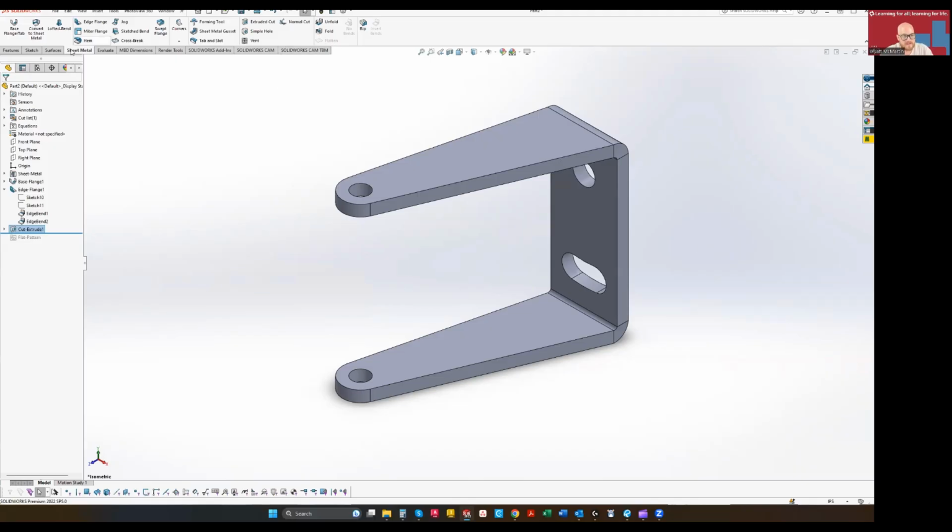However, you'll notice in the sheet metal tab, we don't have an option to flatten it. However, we do have a flat pattern in our feature tree. It just by default is rolled back. So if we just grab this little blue line and drop it underneath our flat pattern, now it's still suppressed here. So it's not bolded like these other ones are here. We can now have the option to flatten our part. We're gonna go ahead and click flatten.